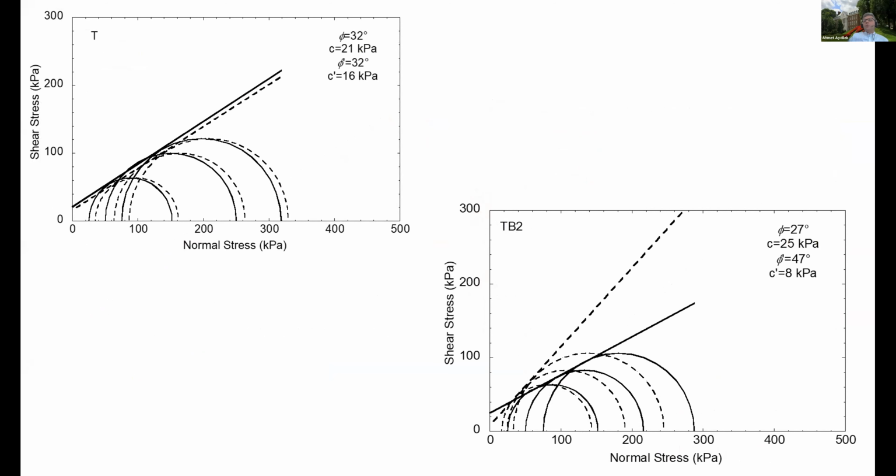And the same is true for the triaxial systems. Now you can see the total as well as effective friction angles, and then the cohesion, a little bit of cohesion present inside the topsoil. Then when you go to the blends, the friction angles also differ.